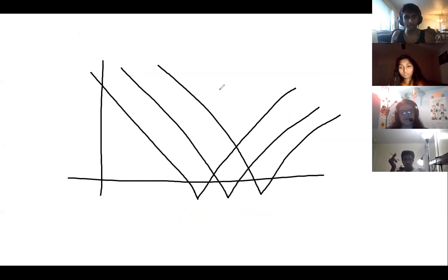Let's say that our operating frequency range is from here to here. What our superimposed graph shows, when you add all the impedances, is that current will always take the path of least impedance or resistance. So it doesn't matter which part of the capacitor or the circuit has the least impedance, the current will go through there. So all the current sees is something like this.